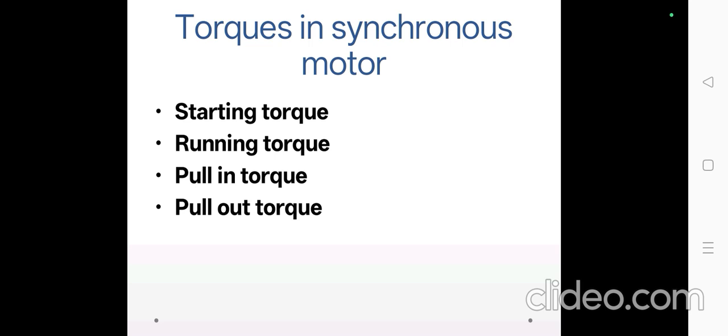Okay. Next one is the synchronous motor connected to the infinite bus bar. The synchronous motor connected to the infinite bus bar behaves similarly for the change in the load at constant excitation. As the load increases, the load angle increases, current increases, and power factor changes. The change in the power factor depends upon the excitation used in the synchronous motor, whether it is normally excited, overexcited, or underexcited.